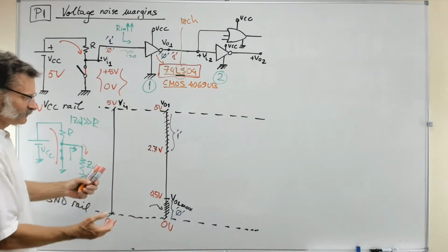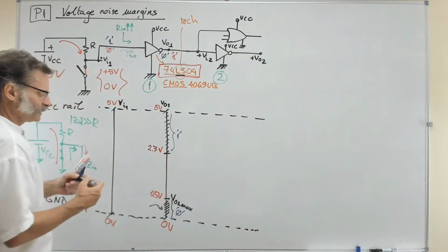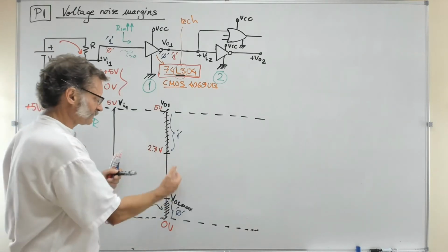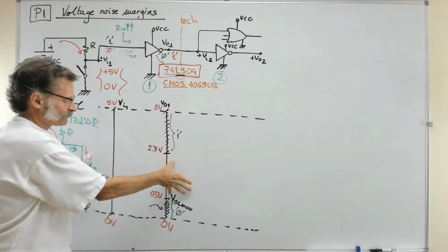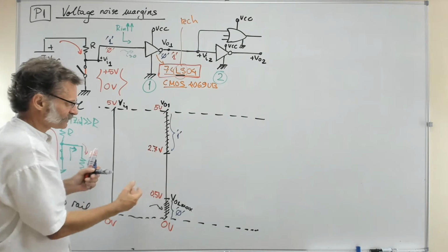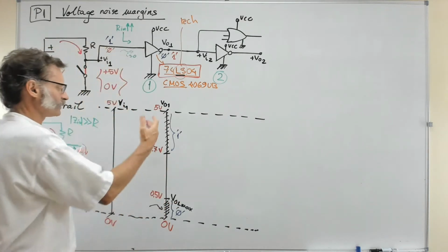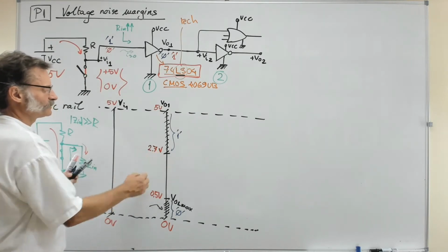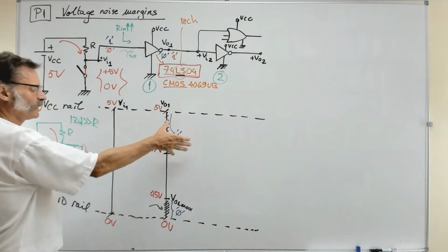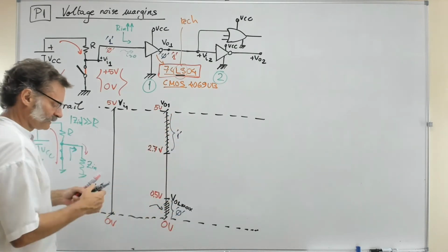In between, if the digital circuit works fine, you will never have to expect that from the output of the gate you get nothing. You will never get such voltage like 1.5. If you get that, it is because the gate is broken or something. So in normal operating conditions, you will expect here a 1 or a 0, and this is the range of voltages that is a 1, and this is the one which is a 0.